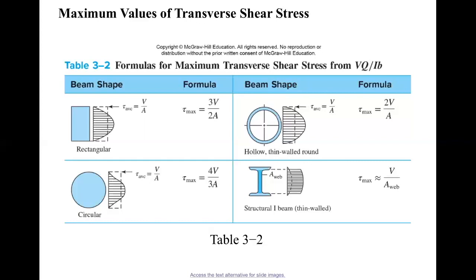However, if the beam, the shaft, is a short shaft, transverse shear stress is more significant. So it depends on the length, right? The short shaft or long shaft, and the role of the transverse shear stress in the design is different. And we'll give you more details in the future.